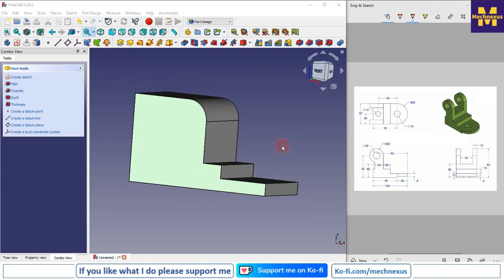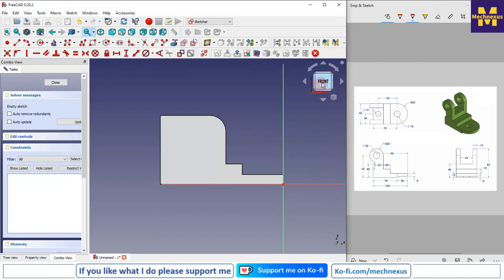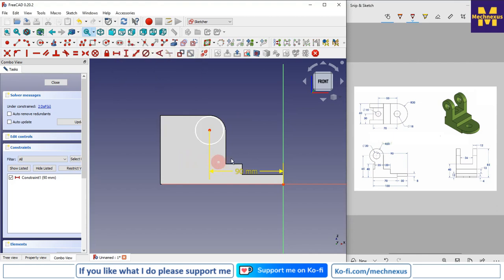So I have selected the face and I will create a sketch and switch to the front plane, and now in the same way we will draw this circle. So I will select circle and draw one circle here, and I will select this and this, and I will give the horizontal dimension which is 90, and the vertical position is 65.